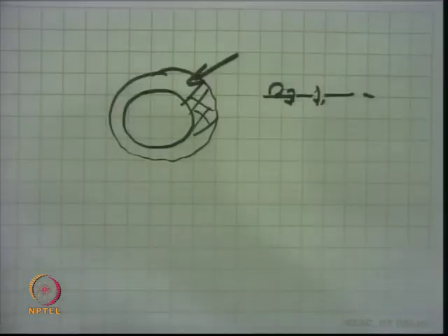where you have simple plates or a wire placed inside, a non-porous type of material, and then on that the catalytic active material is impregnated, and at that time the reaction is only on the external surface. So, this is just a thin film, or a small thickness, so that the diffusion resistance is kept at its minimum, and that is a washcoated type of catalyst which can be used in this trickle bed reactor, because these are mainly mass transfer controlled processes. The kinetics has less role, the kinetics is very fast.